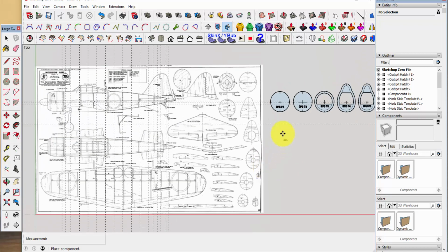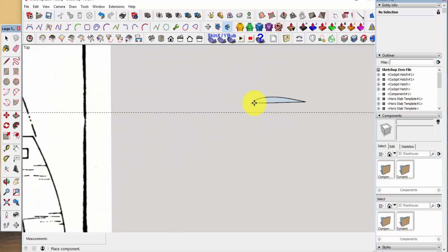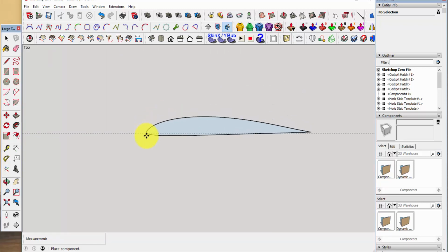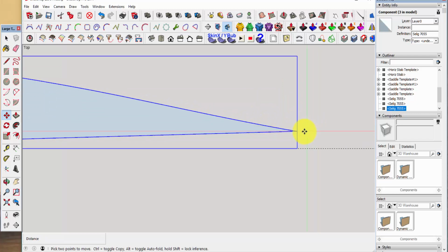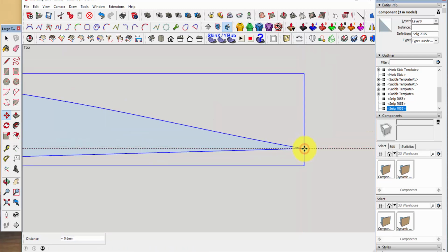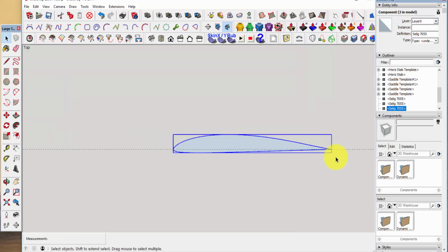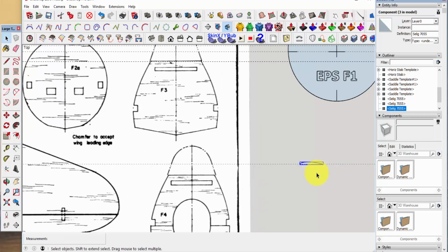All you need to do now is drop it on the image, and again, to make this easy, I'll just come in here to one of the lines that I know is on the face plane of the drawing, and we'll take that and I'll move this very end point onto that line. Now at least I know that it's on the ground plane. We're going to move it, but it's on the ground plane right now. And it's a little tiny. Of course, the scale tool is going to fix that.